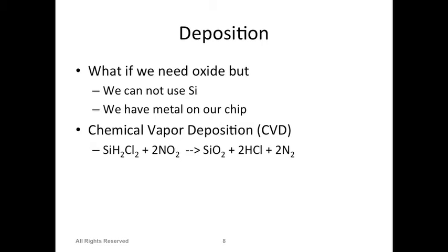What's the precondition for oxidation? What materials do you need? You need oxygen and silicon. So silicon has to be there. If there is no silicon, if there is chrome or other material, not silicon, then we cannot have silicon dioxide by the oxidation process, right? So if we have a surface where we have a metal or other materials or anything else, then we cannot have silicon dioxide there with the oxidation process.